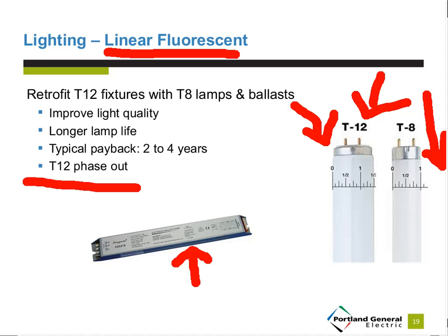The T8s, the technology is changing so fast, and the cost of LEDs are coming down so much that 5, 10 years from now, it might be all LEDs. We're not sure. Right now, T8s and LEDs have about the same cost effectiveness. LEDs are a little bit more expensive. They take longer to pay back, to be an attractive investment. Long hours of operation help that happen if you're interested in LEDs.